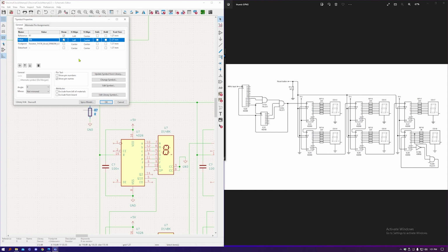Resistors, you've got 1k, 10k in particular. 10k and 100 nano are by far the best values to use if it's not too important. So for a pull up or a pull down, I would always recommend 10k unless a data sheet or something else specifies otherwise. That's useful for reducing what's called the BOM, the bill of materials.